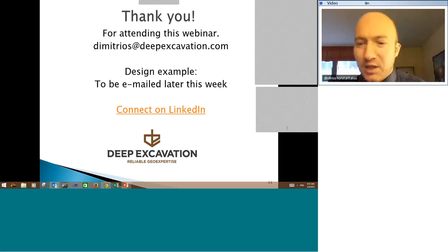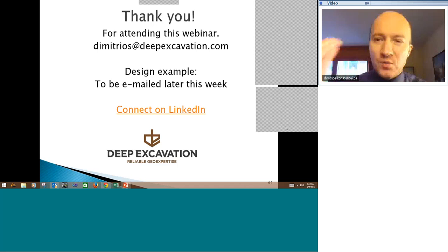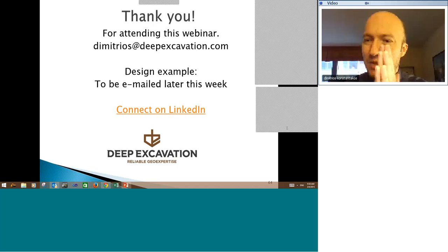What kind of nonlinearity do you keep mentioning? Okay, first of all, nonlinearity is our soil response. It's never linear. It always has some elastoplastic response, where when you press the soil, it won't follow a linear curve of strain and stress, but has a curved approach. So that's the general idea. If you follow just a traditional structural design for deep excavations, you're ignoring all those nonlinear soil interactions with the structure, be that the wall, the tiebacks, and so on.